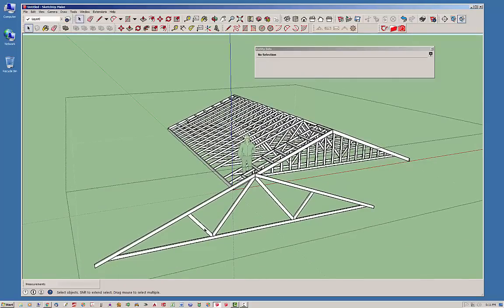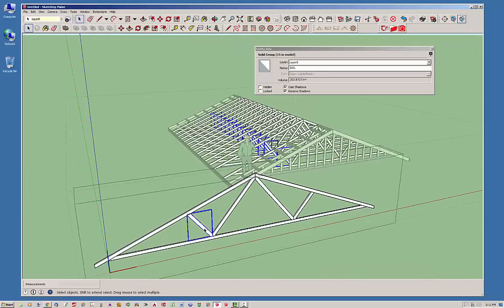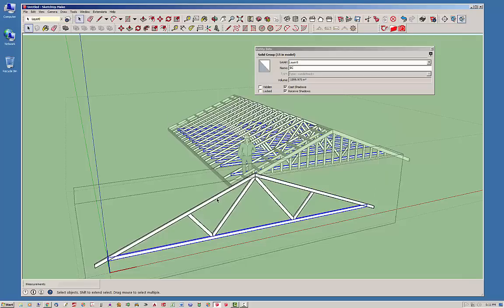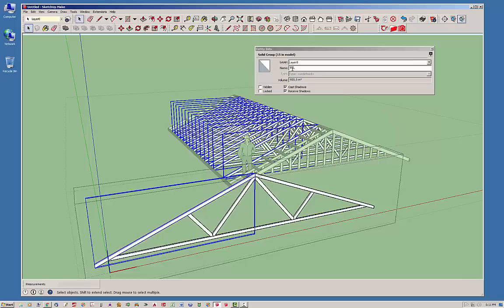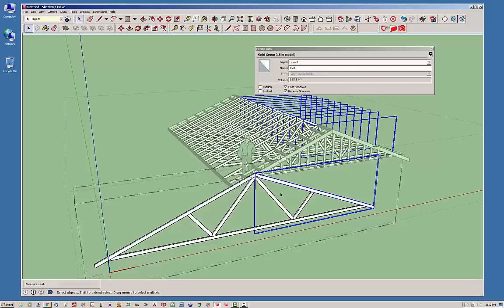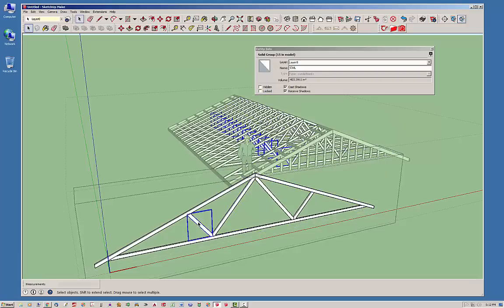If you click into this component, you'll see that we've got different solids or groups that form the members and the chords. This is the top chord here. Here's the bottom chord. Here's the left top chord. You can see TCL, top chord left, TCR, top chord right, and then it goes ahead and members out. Basically, we're identifying each one of these members, and they're all solids. So that's the methodology that I'm using in creating the geometry and how I'm organizing things.